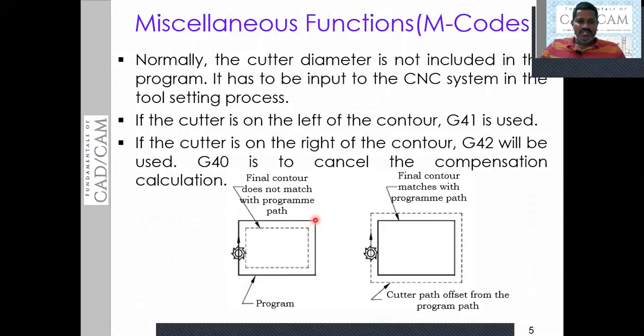exactly the object that we want to machine. We programmed this path. The thick line that you can see here, we programmed to move the tool, and this is the required dimension of the object. When we program exactly in this path, when we use a tool of so and so diameter, the dimensions of the object will be less. Yes, you can observe here.